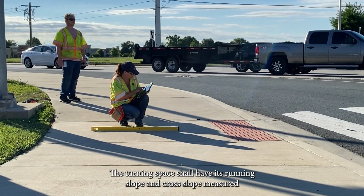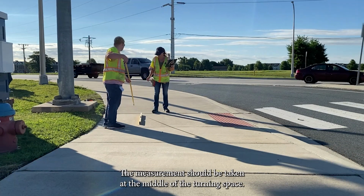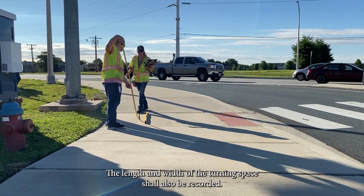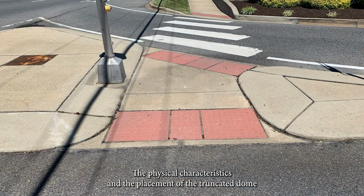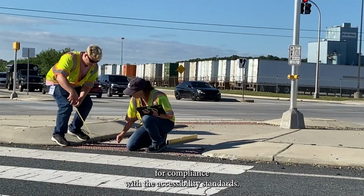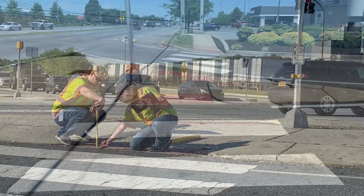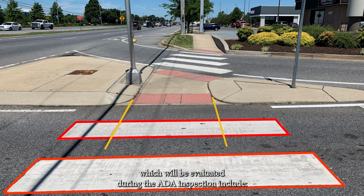The turning space shall have its running slope and cross slope measured and recorded. The measurement should be taken at the middle of the turning space. The length and width of the turning space shall also be recorded. The physical characteristics and the placement of the truncated dome detectable warning surface shall also be evaluated for compliance with the accessibility standards.